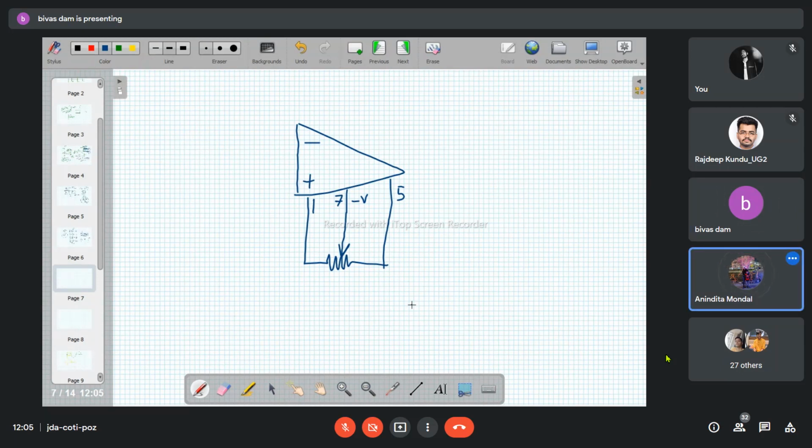Yes, sir. And if it moves towards pin number 5, pin number 5 is becoming more negative than pin number 1. So the relative negative voltage values coming to the level shifter stage through pin number 1 and pin number 5 will try to adjust the level shifter output to either the more positive side or the more negative side, by trying to adjust the output to be zero voltage.